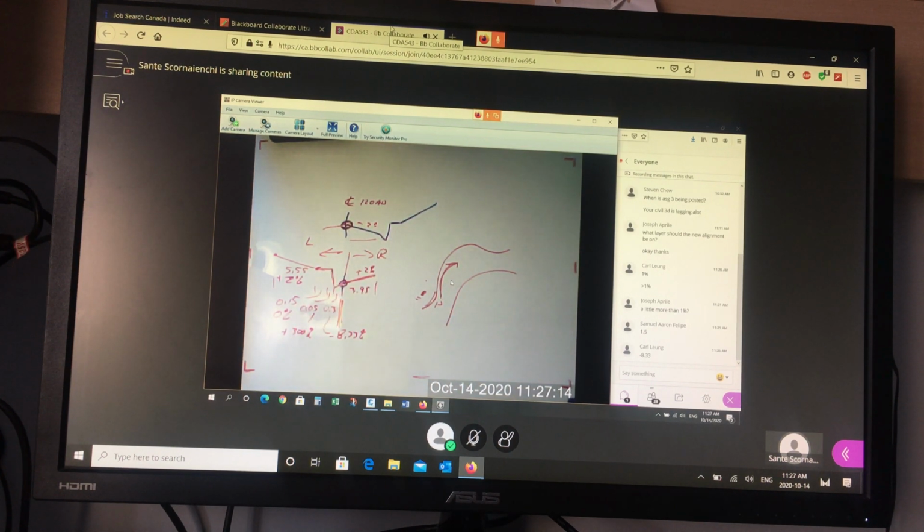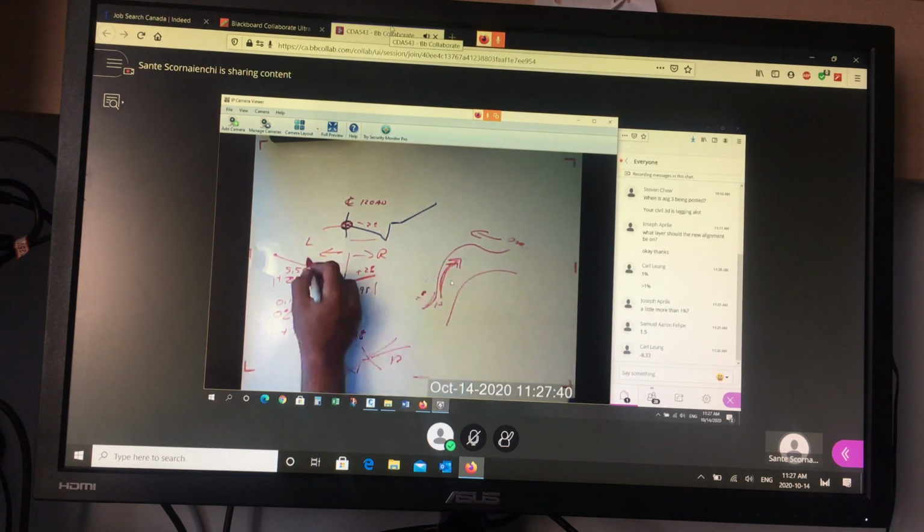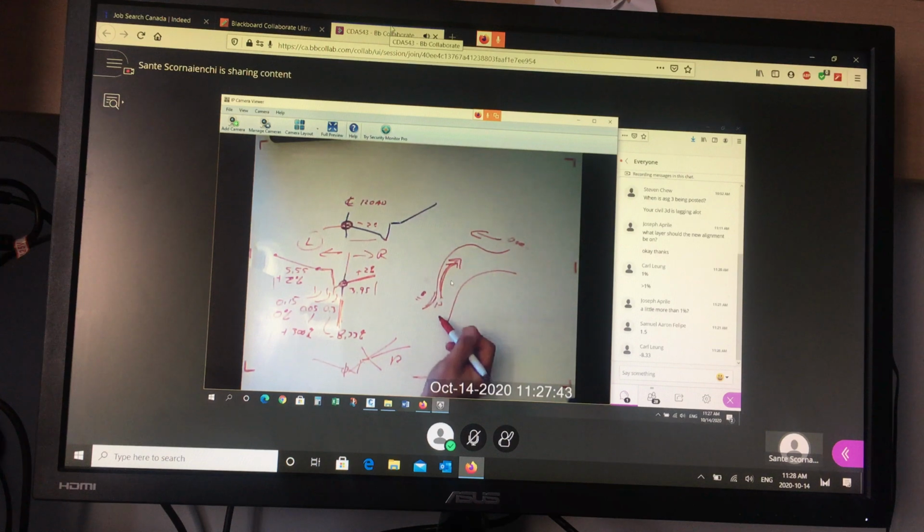Okay? If the alignment was going the other way, if 0 was over here and positive change was going this way, I'd have to create the mirror of this. I'd have to use that assembly point and go up, down, up, across, and backward. I'd have to have the boulevard on the right side. Okay? But that's not what's happening. So you have to make sure that when you're building the parts, you remember how you created them. I know positive change is in this direction, which means the boulevard needs to be on the left side of the road. If you draw this, then it'll be backwards. It won't make sense. So you have to be consistent with your model and remember what's going on all the time.